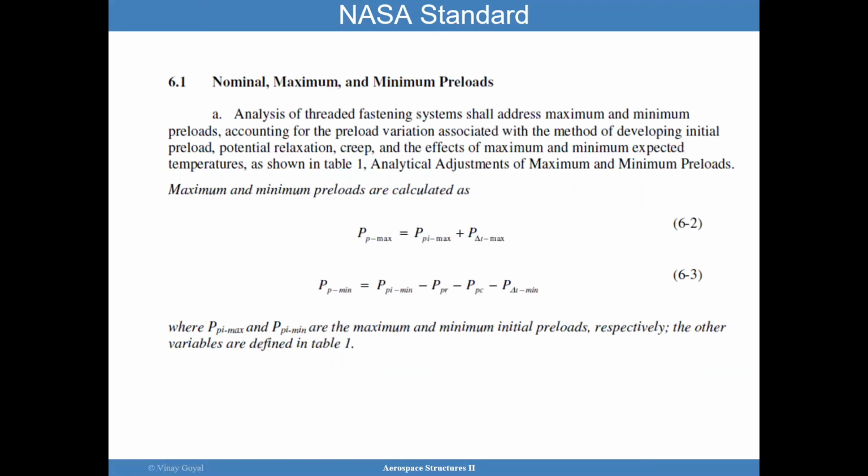It's also important to consider nominal, maximum, and minimum preloads. We have to address for those because you could have those situations, and you could have a potential for relaxation of that preload, creep, and then perhaps the temperatures can affect the maximum and minimum expected preloads. And so it is important to adjust for those situations.